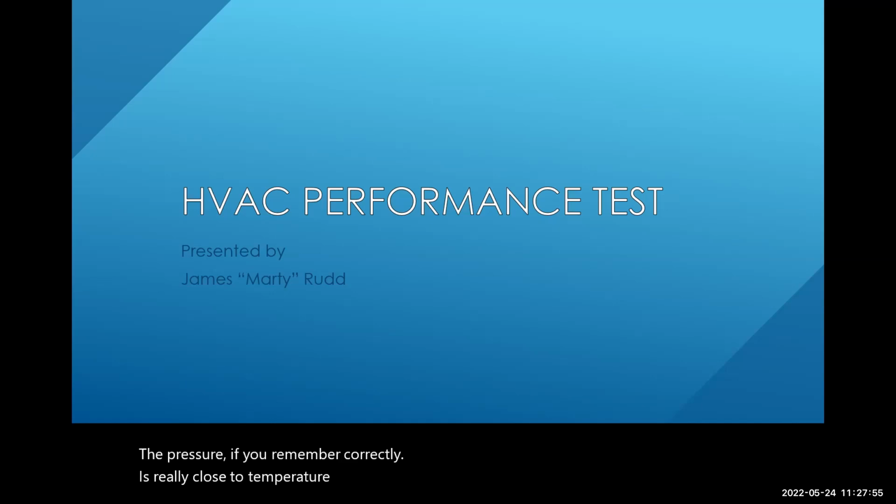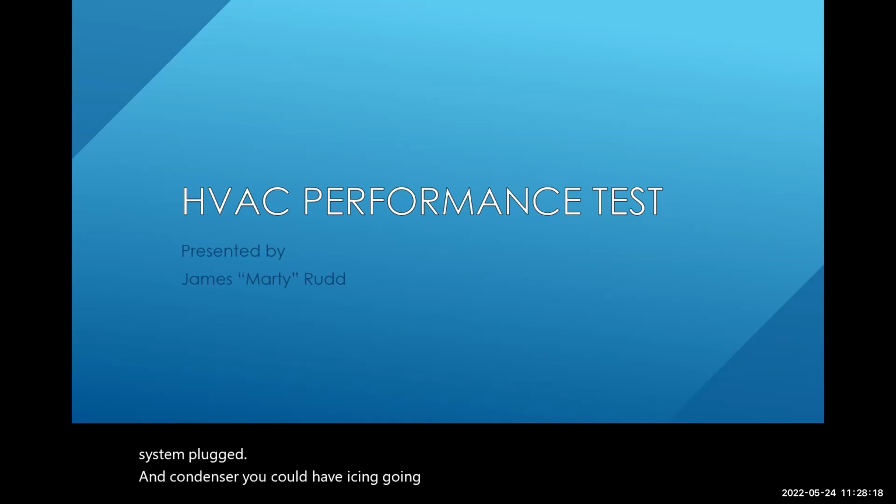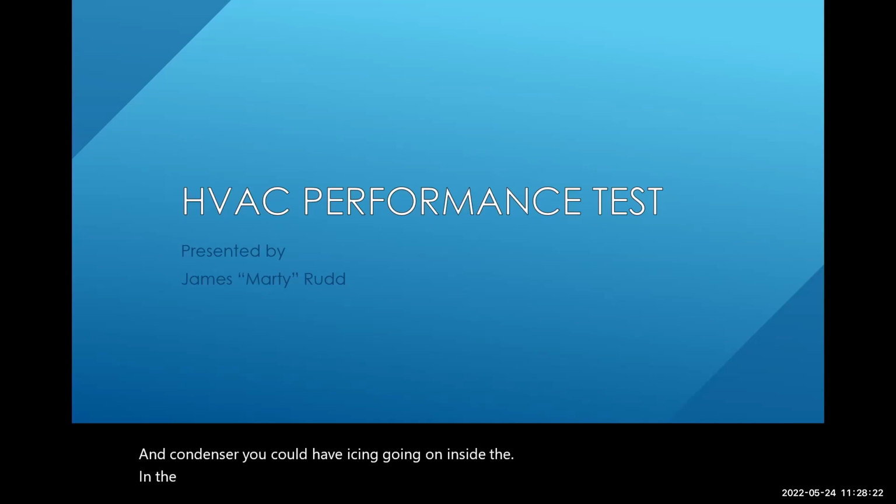So you can actually use these pressures to diagnose a possible fault, either a compressor not working correctly, you could have a plugged AC system, a plugged condenser, or you could have icing going on inside the evaporator. So there's all kinds of things it can do. So let's go ahead and get started.